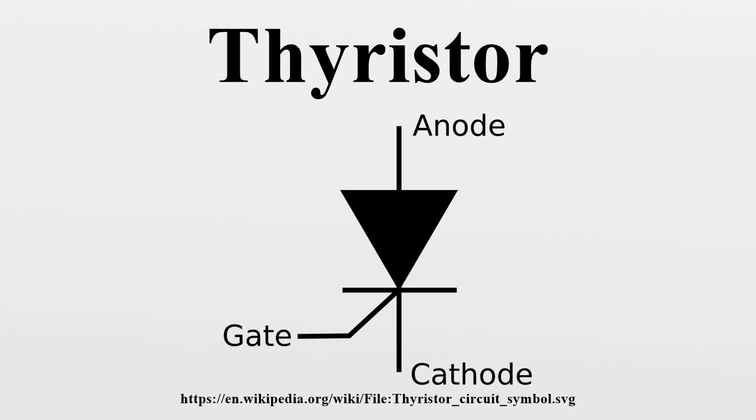Such fast thyristors can be made by diffusing heavy metal ions such as gold or platinum, which act as charge recombination centers, into the silicon. Today, fast thyristors are more usually made by electron or proton irradiation of the silicon, or by ion implantation. Irradiation is more versatile than heavy metal doping because it permits the dosage to be adjusted in fine steps, even at quite a late stage in the processing of the silicon.